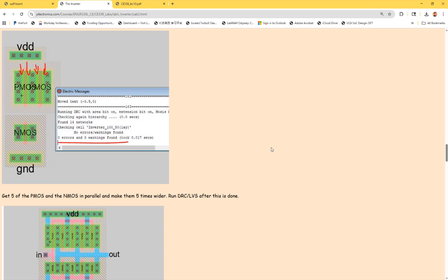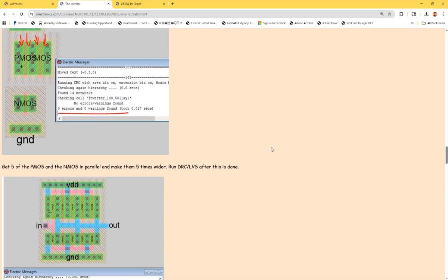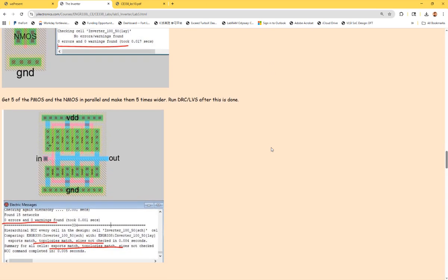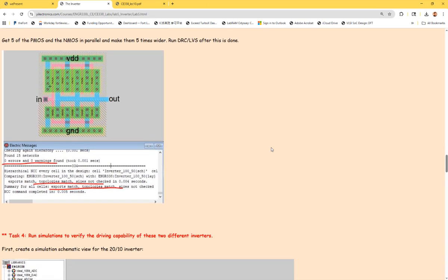And because there will be a lot of overlapping, after you move it to here, it looks like it's working. So the first thing you want to do is F5, right? Just DRC it before you move forward. There will be a lot of errors, I believe. As a beginner, DRC it very often instead of having hundreds of errors until it's too late.